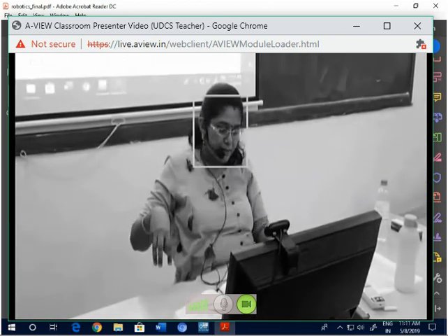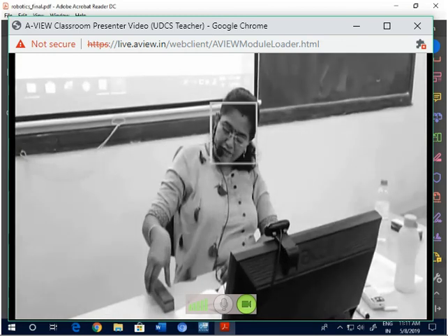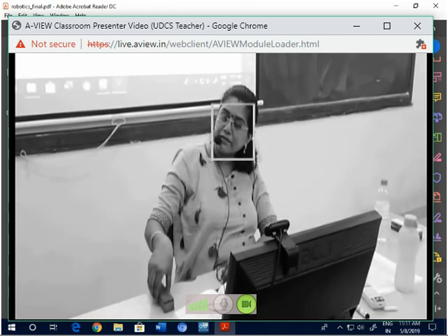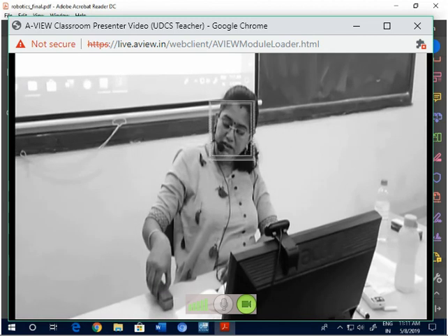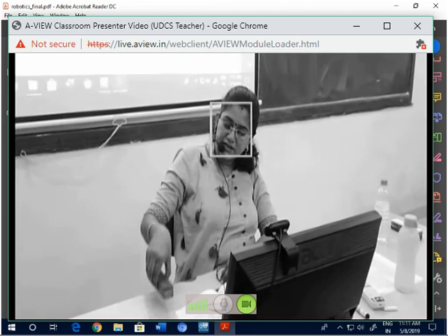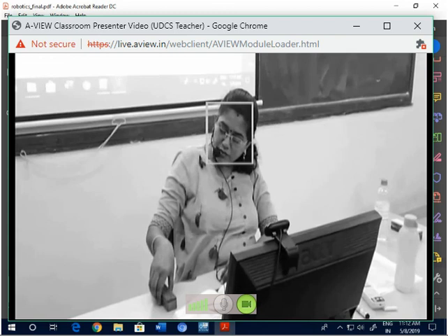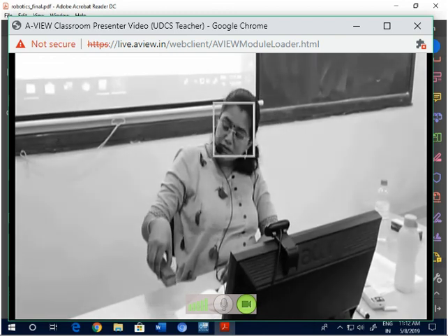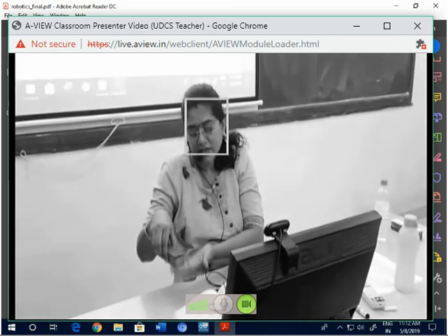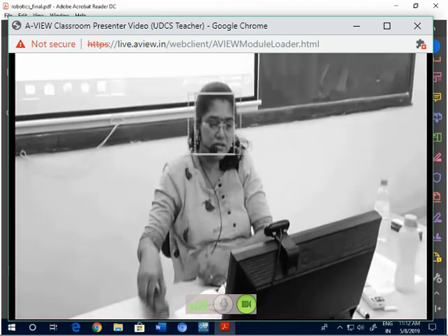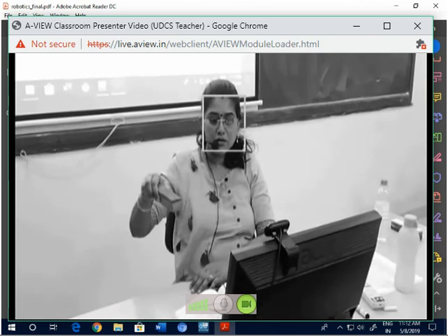The tool orientation at the lift-off point is identical to the tool orientation at the pick point. While picking it up, if this is the tool gripper, I have to compress my fingers to the distance to pick, so the tool orientation doesn't change out here. Only the distance changes. So the tool orientation at the pickup and lift-off will remain the same. Only the distance of the tool from the base changes. The tool orientation remains fixed as the tool moves from the lift-off to the pickup point, to the point which you pick up.